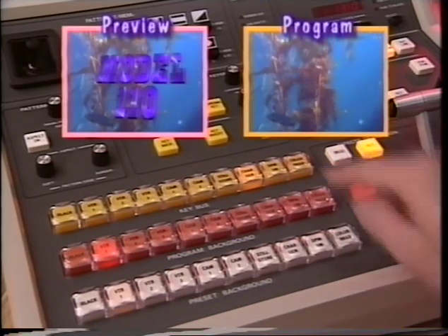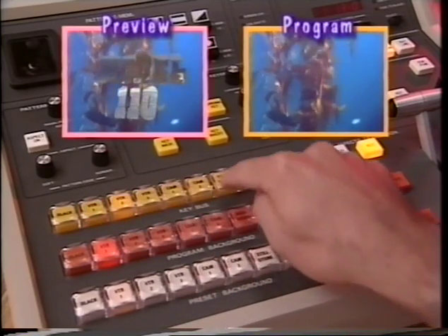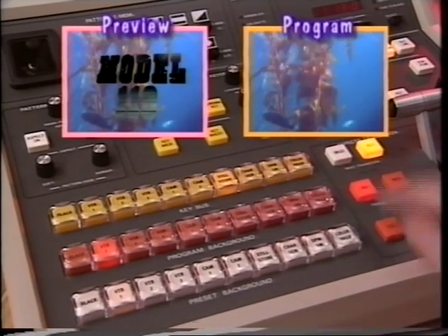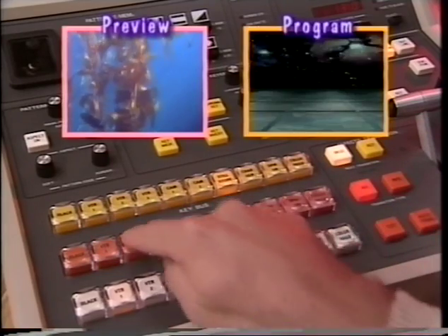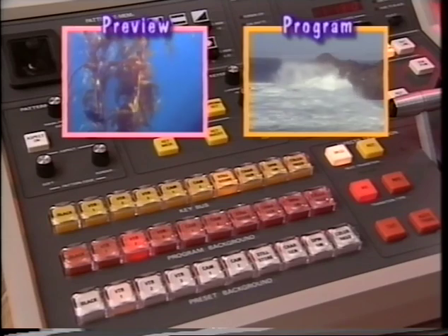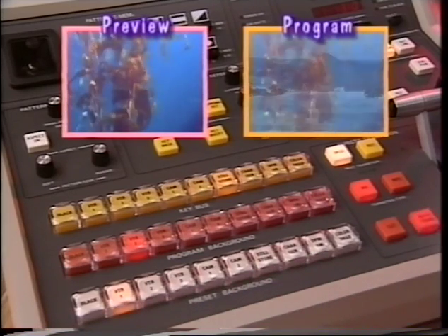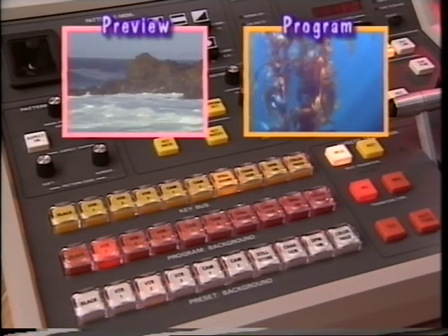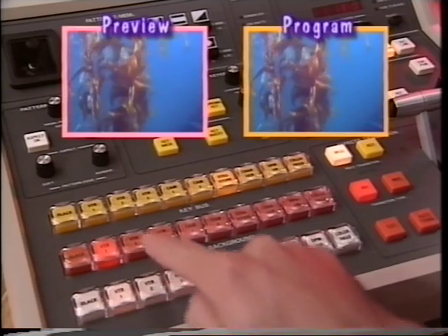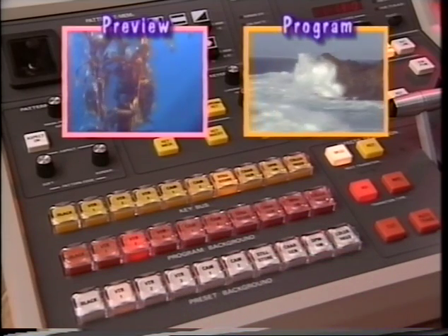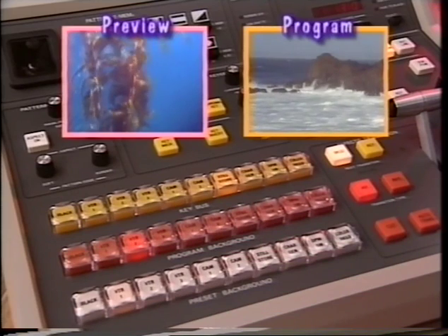The key bus selects video which can be used as the video fill for an effects key. The program background bus selects on-air background video for keys and effects. And the preset background bus selects background video to be placed on air during the next background transition. Selecting a new input on a bus automatically turns off the previous selection, so that only one crosspoint is on at a time on each bus.